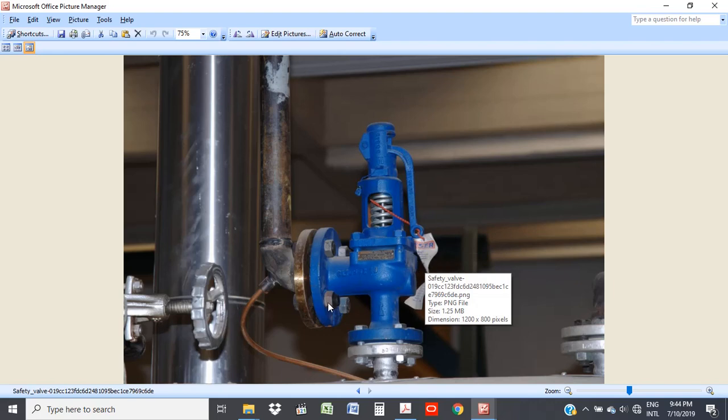Let's say you have a vessel with an operating pressure of 2 bar and a design pressure of 10 bar. Sometimes there might be process upsets, so that if the normal operating pressure is 2 bar, the vessel sees a pressure going to 7 bar, 8 bar, 9 bar, and then it hits 10 bar. At 10 bar, the integrity of the vessel will be compromised. It could rupture. There could be failures in the instrumentation in the pressure vessels. So you don't want it to hit that pressure.